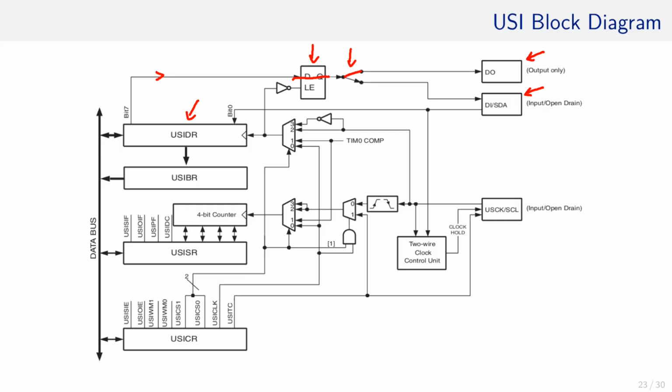So the RX wire is never used to transmit data back to the original transmitter. The situation is different for I2C, in which we have an SDA line, which is used by the master as well as the slaves to transmit data. Since this wire is bidirectional, the outgoing wire will be connected to the digital input pin, like in this scenario.